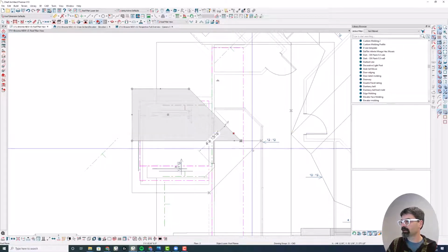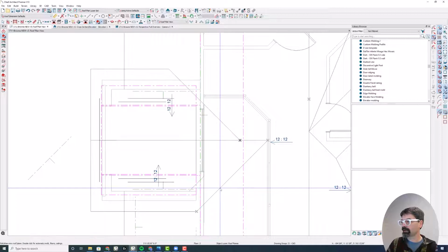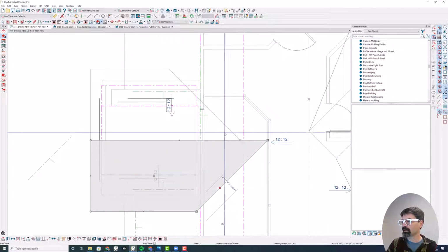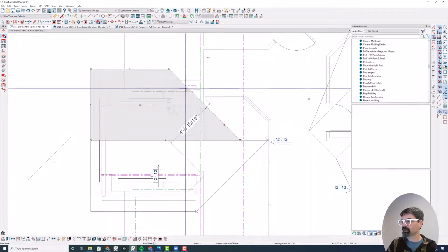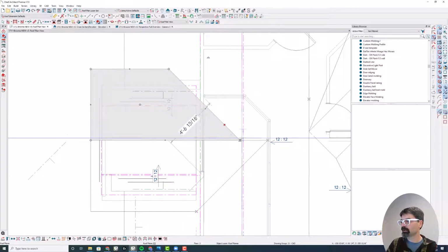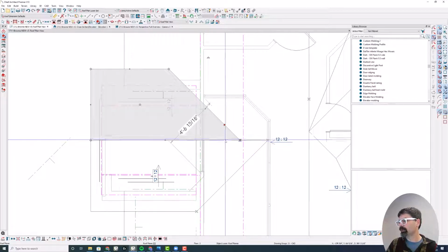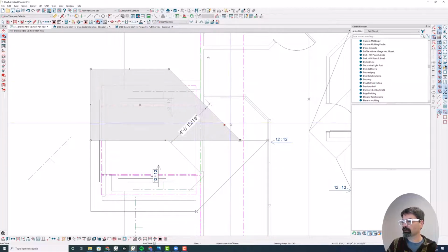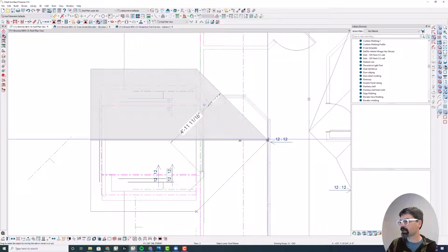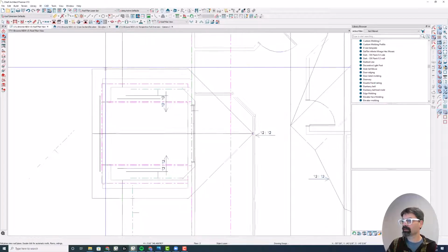On this side, notice I have an intersecting point show up here because I had this roof plane selected, and I clicked on the intersecting line. This valley intersects this roof plane right there. I already knew that, but because my ridge is the same height for this plane as this plane, and I know it's at a 45, I can just drag this valley out to snap to that endpoint. Once again, go to my toolbar or go to CAD, Points, Delete Temporary Points, and it's cleaned up.